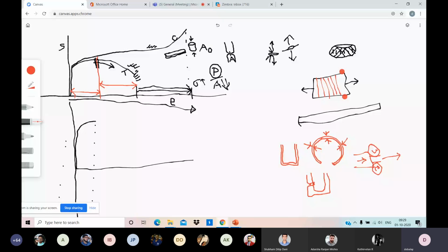You want uniform thickness, and that's why when we do forming operations, even if we apply some tension processes, stretch forming, deep drawing, we have to deform up to this point, and we should not cross this point, because in that case, under tension, there is a possibility of necking. And from the necking, when you pour in your Coke or Pepsi or whatever beverage, under pressure, that portion will leak. So that is the importance of uniform elongation.